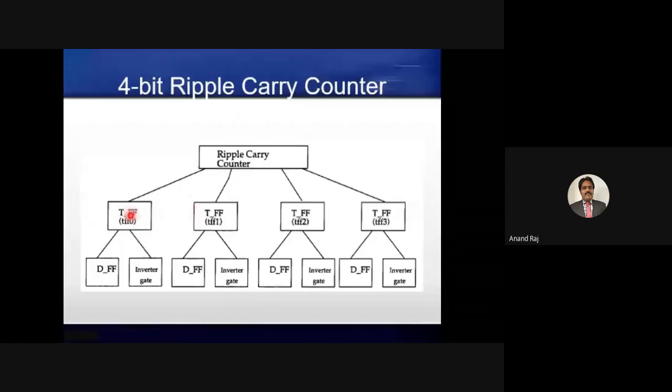The T flip-flop can be further realized using a D flip-flop and an inverter gate. So each one is subdivided into these two component modules. So this is how we specify the top-down methodology.